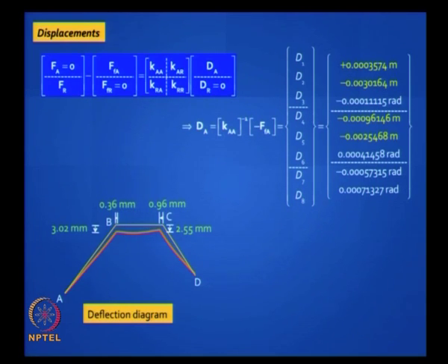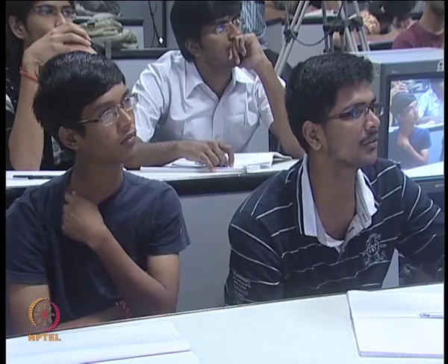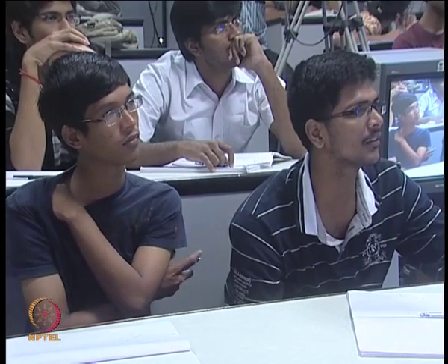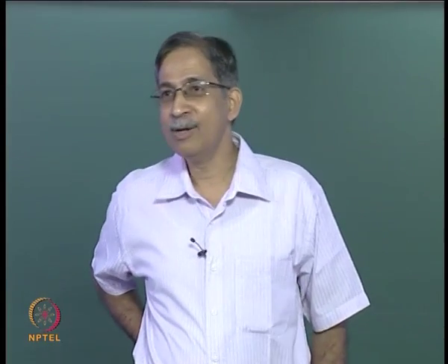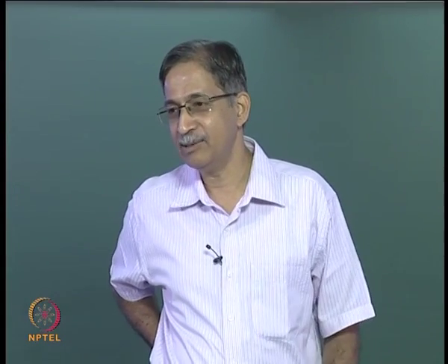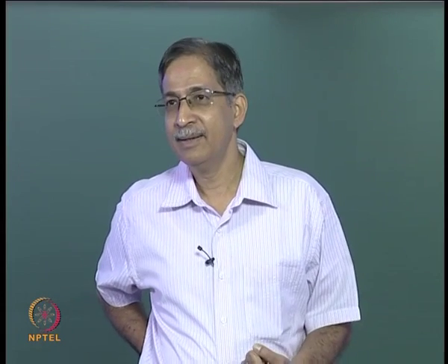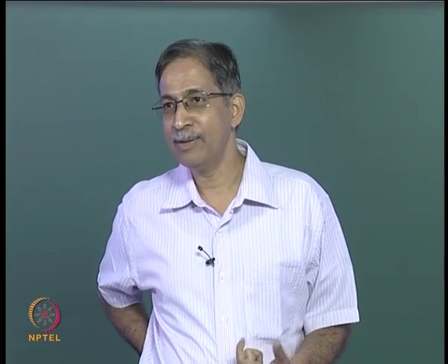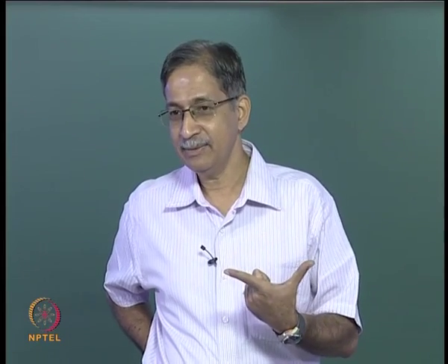The displacement we got. Yeah, we calculated e0 for element 2, which was 1.32 mm or something, right? Yes, sir. Now, subtract from it and you see the value. What do you think you'll get? Negligible. So let's just look at element 2, e02 for example. You can do for element 1 and 3 as well, but let's just take the second element because it's nicely horizontal. So e02 was 1.32 mm, and if you want to find the final elongation, which you can get from D4 minus D1, right?